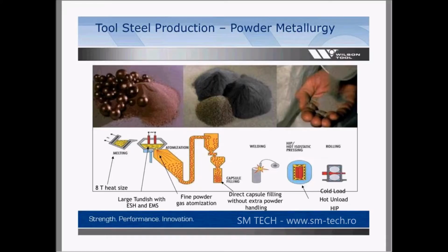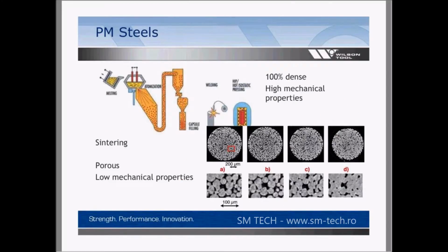And then from that point, it'll go back into the same method everywhere else, so it'll get forged, rolled, and run through a grinder again for the bar, and continue along that process. Another little tidbit about powder metals here is the sintering process. This is where the dense structure minimizes the inclusions or the voids that are common in the commodity grades, which is where your carbon can get in the way. The carbides themselves are now very small, very uniform, and they adhere better. So when you use that sintering process, they get a solid bond amongst individual carbides, creating a better flow of that material.